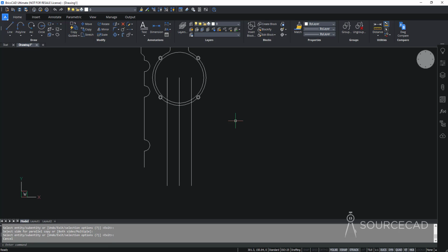Okay, the second offset distance is 2 units. So I'll go to offset again, and let's type offset distance of 2, and I'll make an offset of this line right here. Okay, that's the second offset. And I'll add a third offset as well. So I'll go to offset, and this time the offset distance is 2 again. So 2, enter. This one should be offset here and here. So we've got all the offsets that we need.